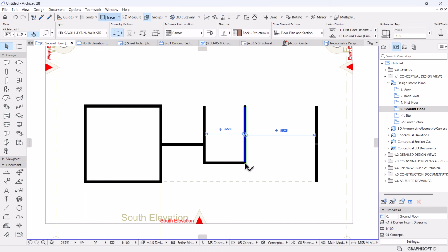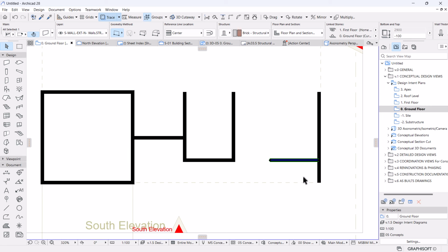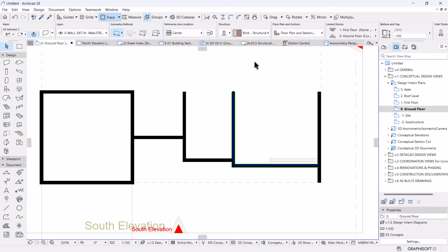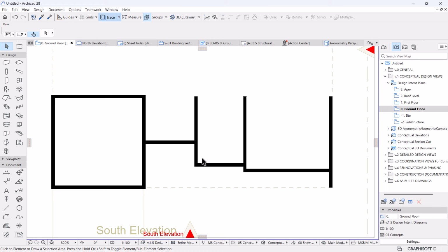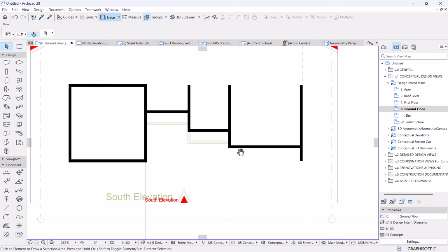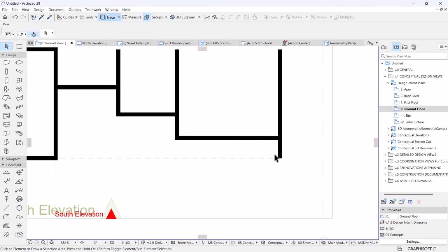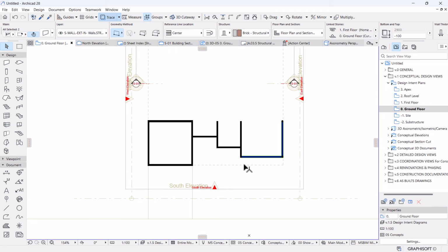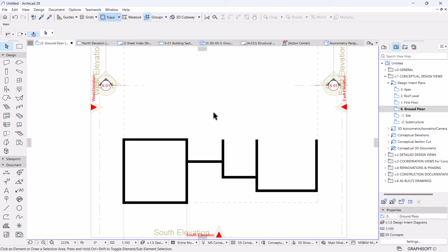And for the family room space that I'm going to create, let's also Control Shift D and place your wall there. And then this, I'm going to set it around from the boundary around 1, 1, 1. And let's select these two and also intersect. I don't think I have that. I might move these two back by a meter, then trim off that. Perfect. This is the kind of effect I want to create with the entrance of the building. Something like this.